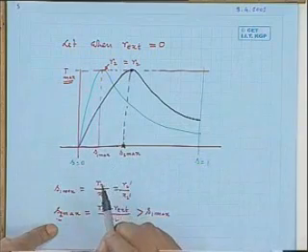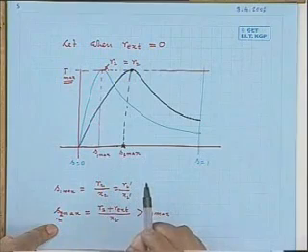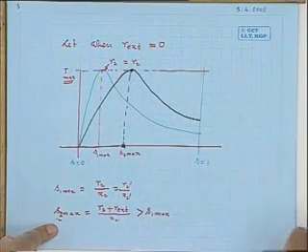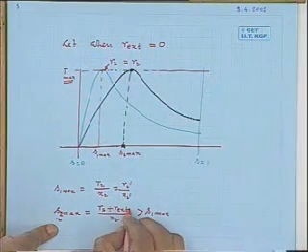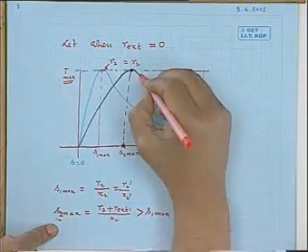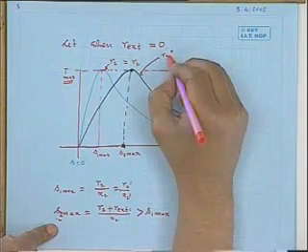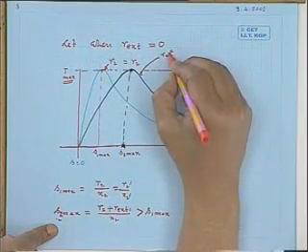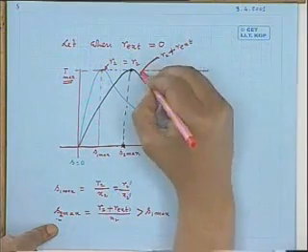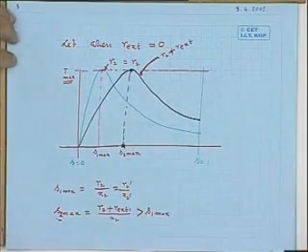Okay, the slip at which maximum torque occurs has shifted towards the right. So this is, suppose, R external 1, in this way I have connected. This curve corresponds to the new R2, that is R2 plus R external. This is the rotor resistance corresponding to this curve.